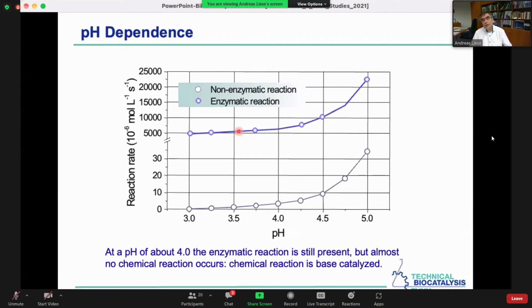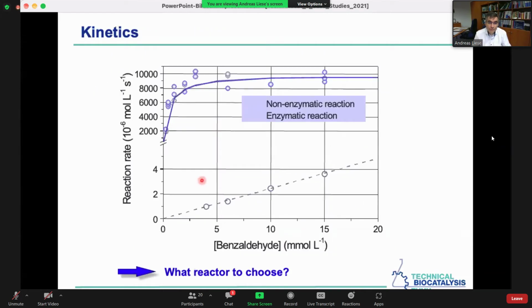So we know we want to have acidic conditions, we want to have low temperature, we want to have a CSTR operation so that at the end of the day we have high conversion. So let's put this into operation with this knowledge.